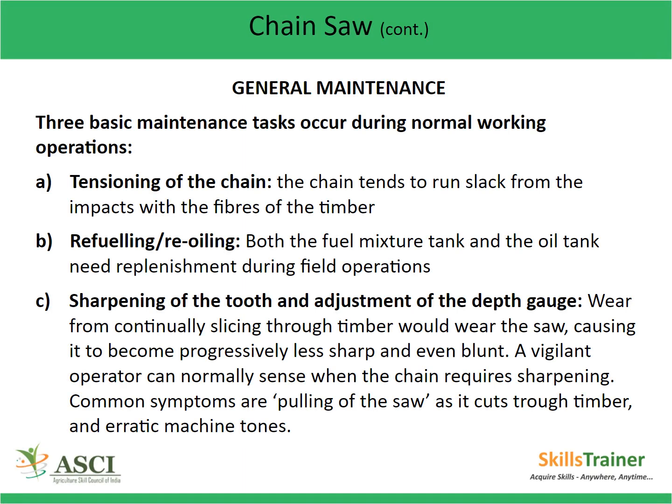General maintenance. Three basic maintenance tasks occur during normal working operations: tensioning of the chain, refueling or re-oiling, and sharpening of the tooth and adjustment of the depth gauge. Tensioning of the chain. The chain tends to run slack from the impacts with the fibers of the timber. Refueling or re-oiling. Both the fuel mixture tank and the oil tank need replenishment during field operations.